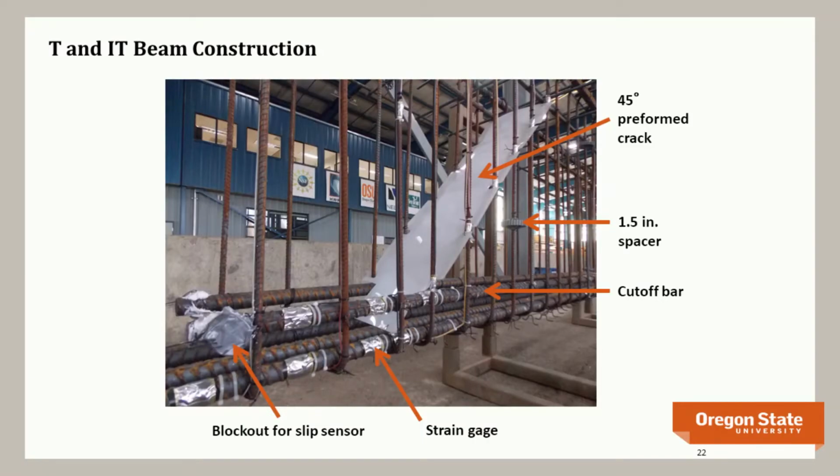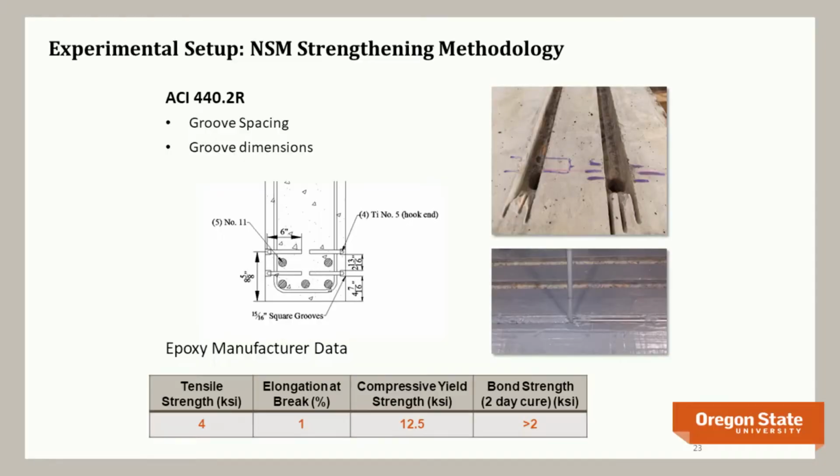We try to make this really hard on the girder. We actually cast in a piece of polycarbonate plate to represent the diagonal crack. So we've taken away any of your aggregate interlock in terms of the shear contribution of the concrete. All you get is dowel action in the compression zone as well as whatever you've got for stirrups. We do that because that allows us to know exactly what the equilibrium conditions are at the termination point of that crack.